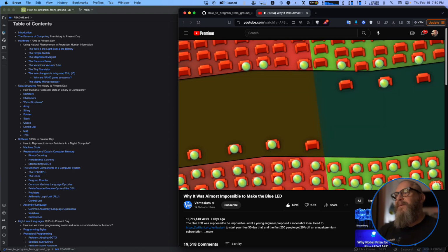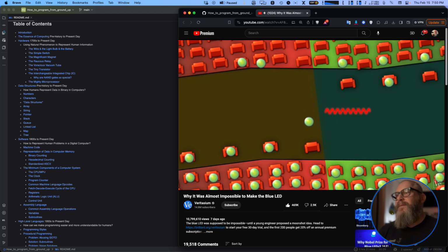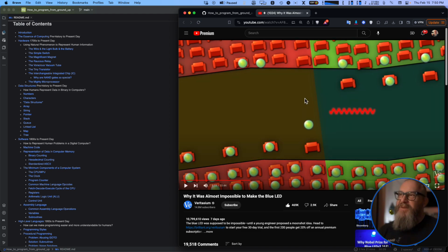When an electron falls from the conduction band into a hole in the valence band, that band gap energy can be emitted as a photon. Right. So when it falls down here, just the way the natural crystals are formed, it comes out as an infrared photon. That's why they didn't know about this activity until they had a way to detect photons coming off it. But it was all just, oh, this is interesting. How can we make this better? And it's just been a continuous process of that stuff.